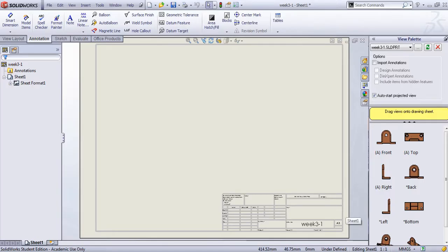I would like to explain that when you create your geometry, your model in the parts section of SolidWorks, you have to pay attention at the beginning to what side is your front, and in what plane you have top and you have side. From there, it will be continued and transferred to here. However, there is a way you can change it, even though you didn't set it up the way you want. In this case, I did it correctly.